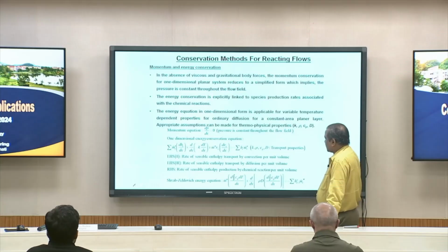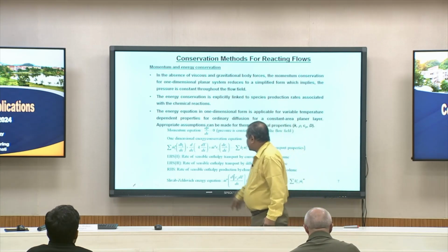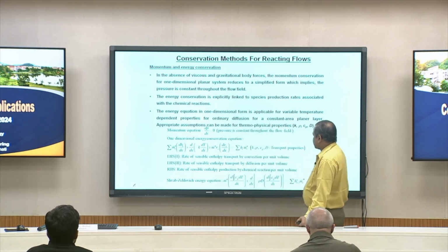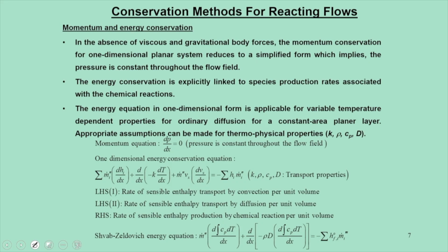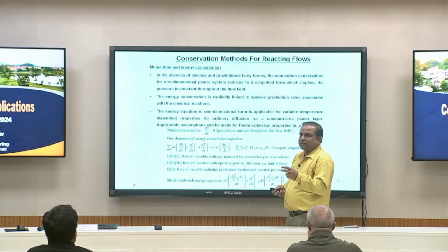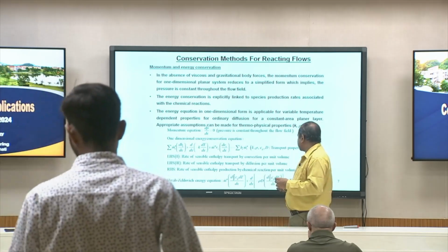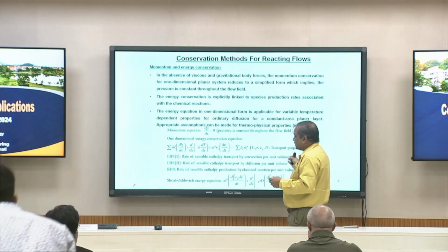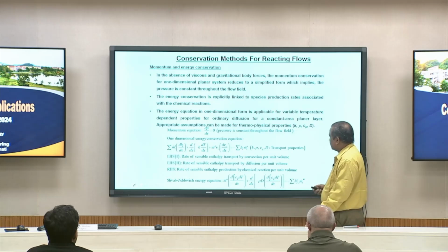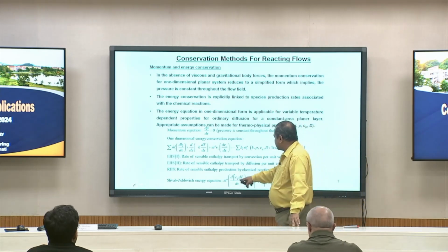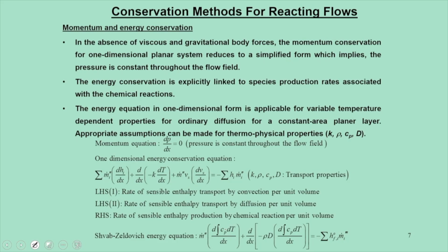One simple model is the Zeldovich energy equation, which takes care of the variation in the enthalpy, which is a function of Cp and T. Cp also changes during this process. Normally the Cp value can be taken to be a constant within 1000 degrees, but beyond that accuracy drops down. So both Cp as well as the temperature effect have to be included.